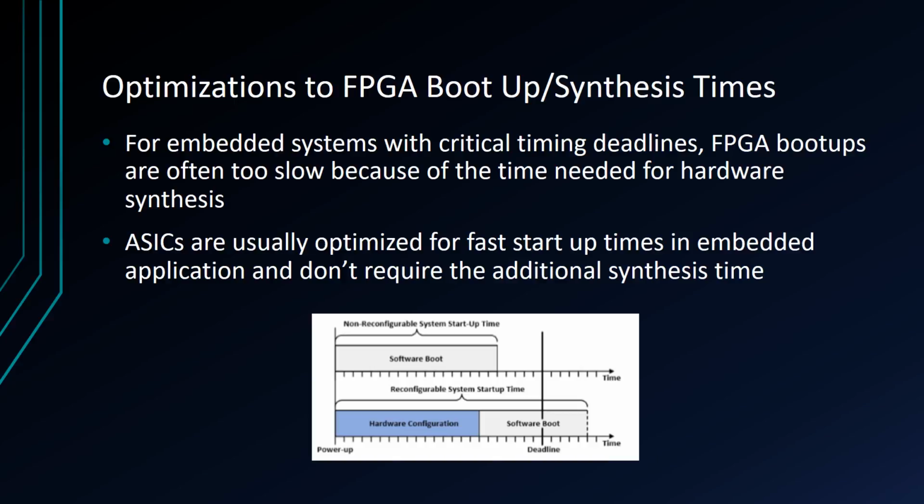And then finally, an interesting optimization I looked at was in optimizing FPGA boot up and synthesis times, and this is specific to embedded systems, where there might be very strict timing deadlines and tasks to be done at startup. Today, FPGA boot ups are typically too slow to deal with a lot of these system requirements. As you can see from my diagram, the FPGA is considerably slower due to the time needed for hardware configuration compared to, say, an ASIC.